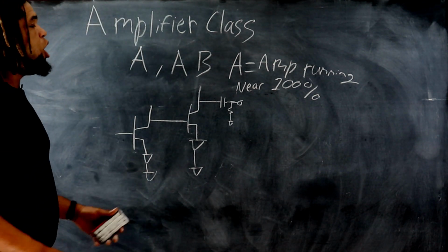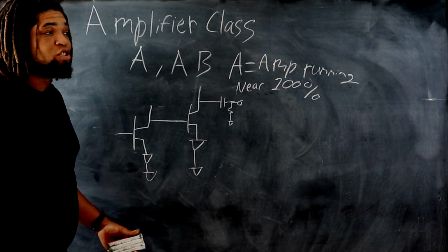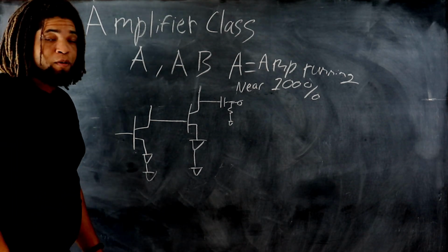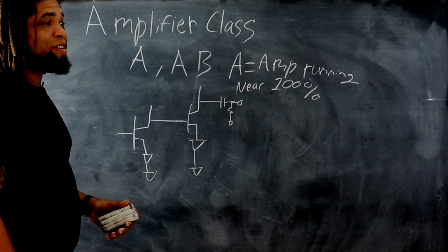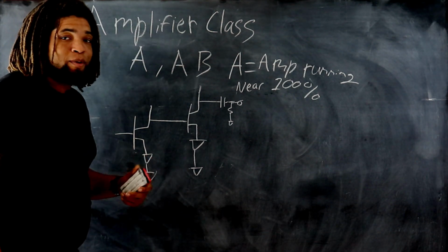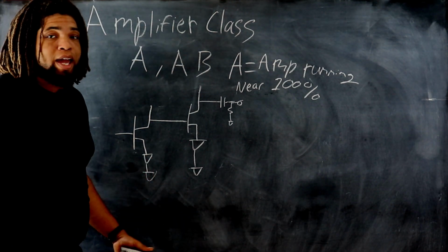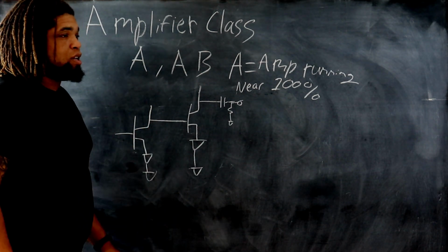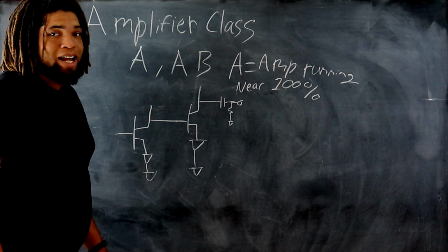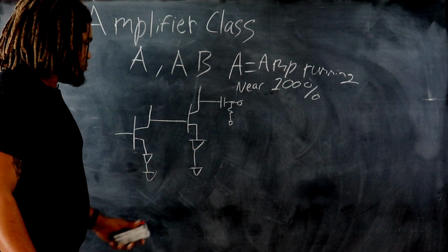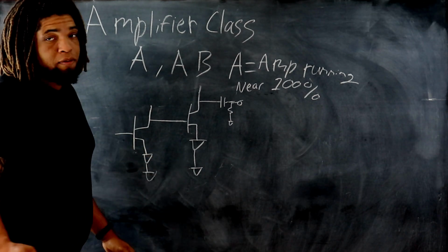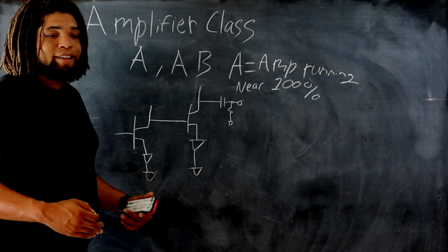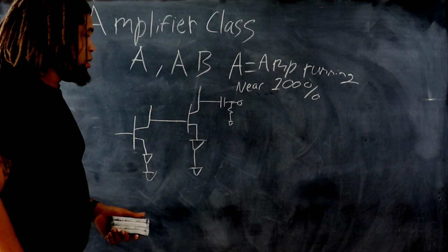Well, unlike vacuum tubes, which actually enjoy a bit of heat, because they are thermionic devices that actually need heat to operate, though excessive heat can degrade them, transistors, on the other hand, do not need heat to operate, but actually derive heat from being inefficient. So the hotter a transistor runs, typically the less efficient that topology is.